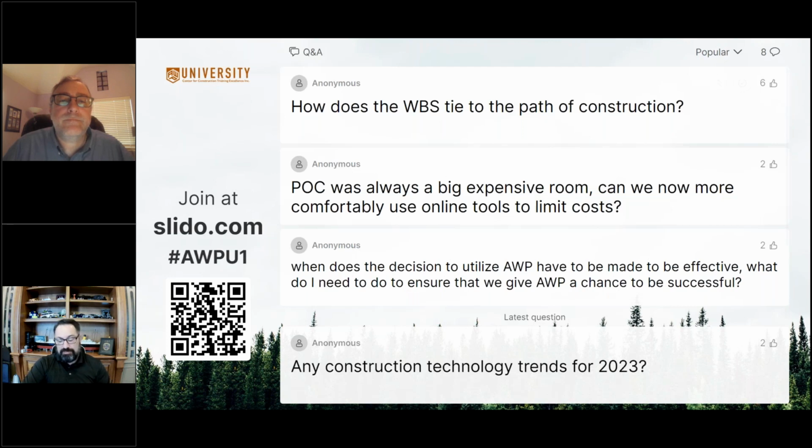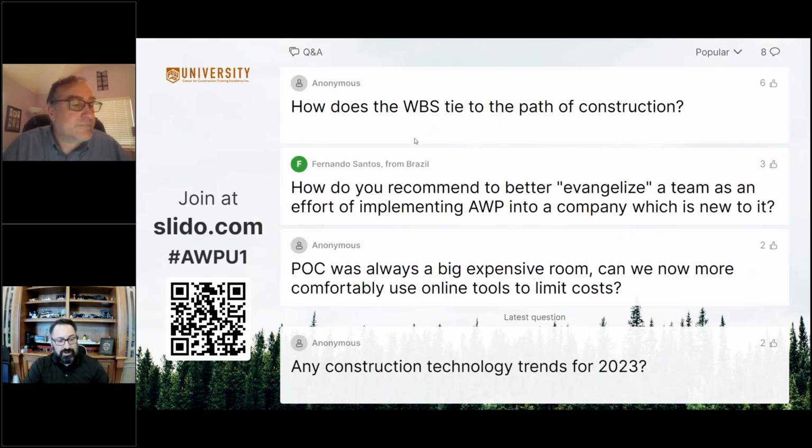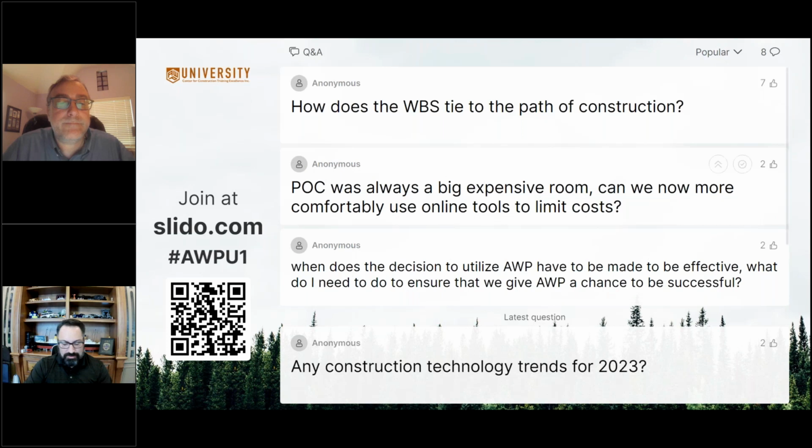When you're utilizing an AWP methodology, regardless of how you're planning your path of construction, if it's an AWP implemented project, your WBS structure should reflect the breakdown structure of the work packages, CWA, CWP, EWPs tied to it, and ultimately IWPs. Now, the IWPs in the schedule can be a controversial topic. We won't go there right now. But that WBS structure needs to be tied to your costing. It needs to be tied to how you break down the model. Before you get into a path of construction, if you don't understand the buckets, it's tough to fill them, right?